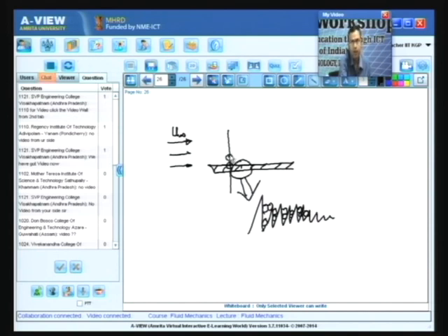which is a little bit away from the wall, the velocity there is definitely not as large as u infinity. Why? Because it still understands the effect of the plate. How does it understand the effect of the plate? It is not in direct contact with the plate. So, how does it understand the effect of the plate? There is actually an invisible messenger in the fluid which makes the effect of momentum disturbance propagate through the fluid.